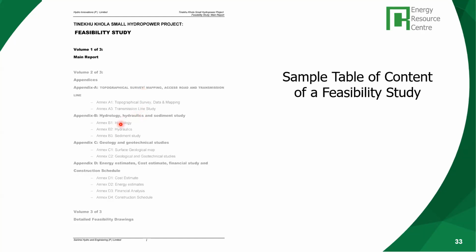So you do a project-specific topographical survey using theodolites and other survey equipment, GPS equipment. Based on that, you prepare the map. And this is prepared maybe in 1 in 1,000, 1 in 5,000, even 1 in 500 scale map. Okay, this is the first one.